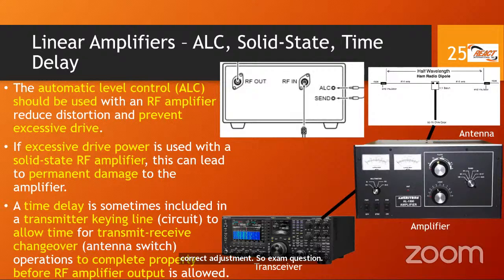All right, so a couple other bullet points that we need to know for the exam in respect of linear amplifiers. One is that the ALC should be used with an RF power amplifier to reduce distortion and prevent excessive drive. What does that mean? Let's break that down a little bit.